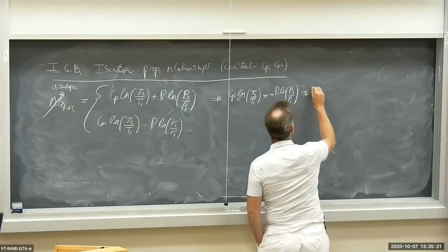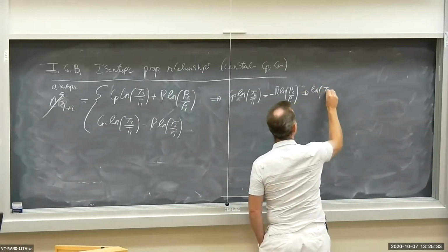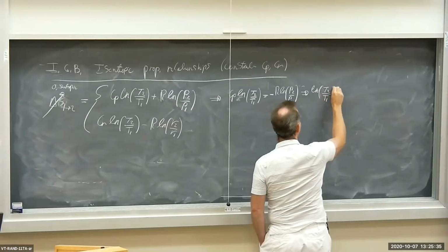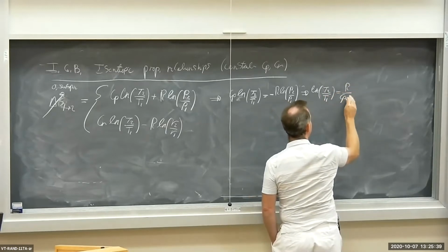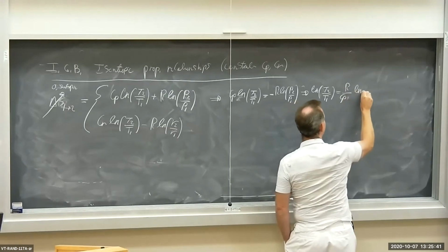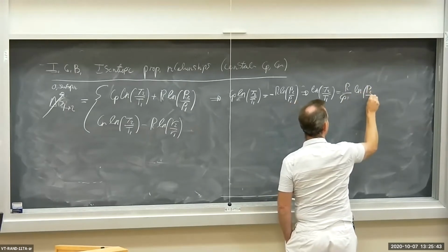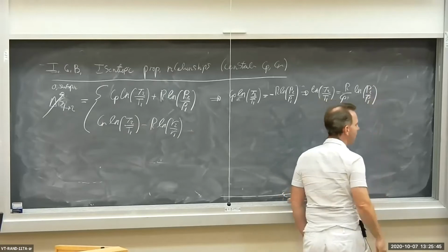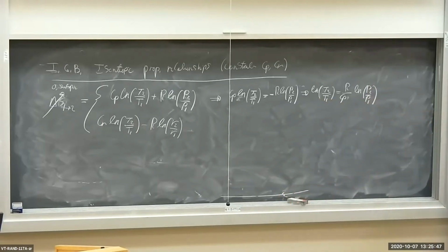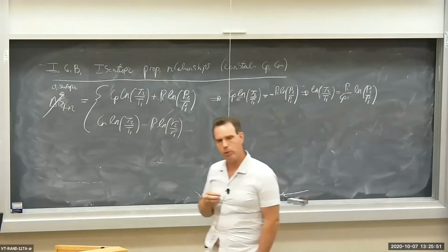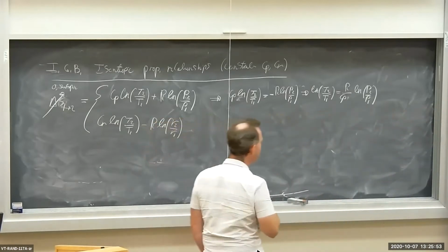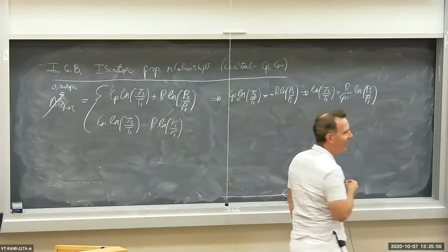So I get ln T2 over T1 equals minus R over Cp ln P2 over P1. Okay? Now, for an ideal gas, what's the relationship between specific heats and the gas constant R?